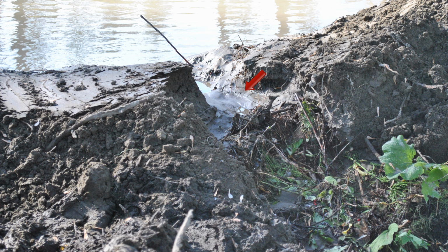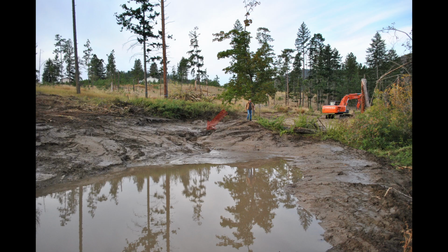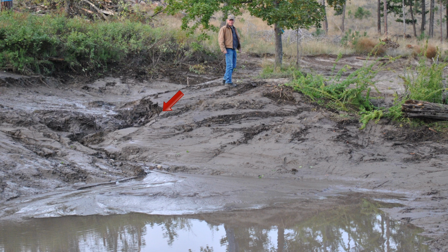I have learned since not to build dams, but rather to excavate depressions to avoid this problem. We also observed that water entering the new wetlands from beneath the surface of the ground was cutting deep channels in the wetland inlets. The water entering the wetlands first caused rills and then gullies to form. This erosion was filling the new wetlands with soil.